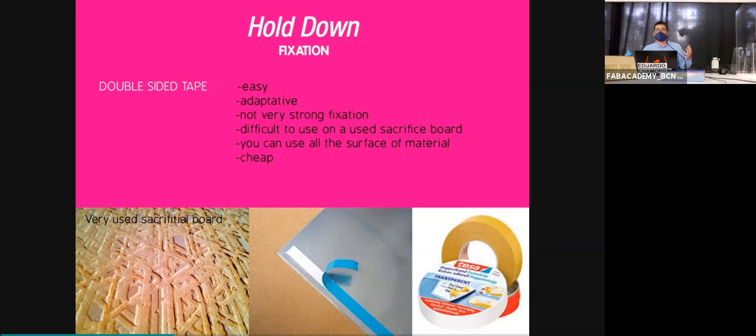But I know cases where, for example, they were cutting pieces of wax, held with tape. The wax, a big block, is around 2 kilos. The material got loose, started rotating on the end mill, flew away like a parabola, and went through the window, breaking it. Luckily, it was the window and not someone's head. So you always try to use a safe hold down practice.